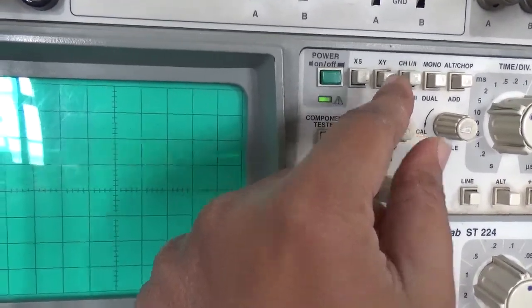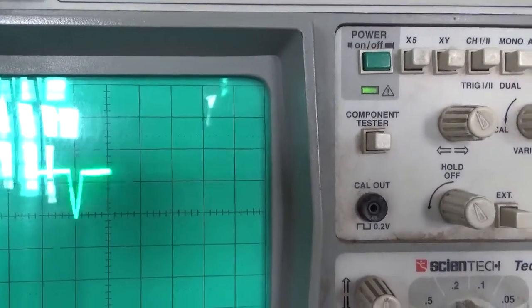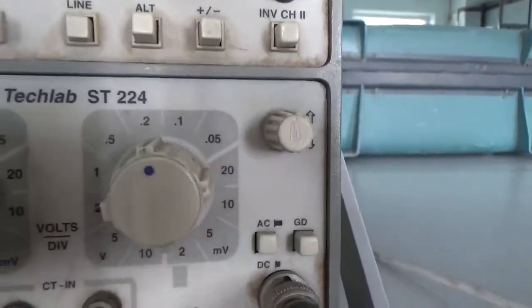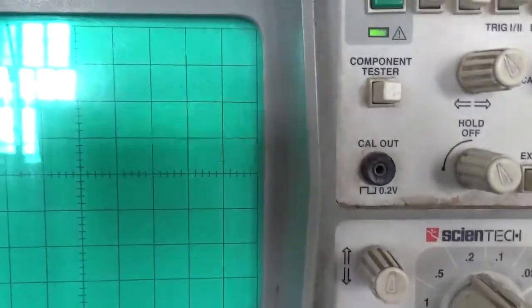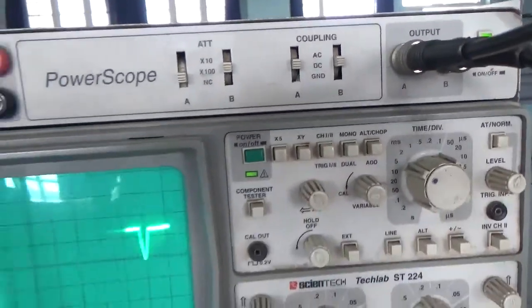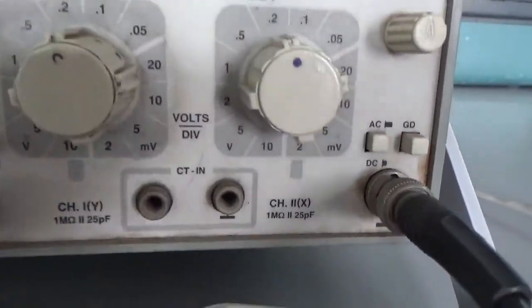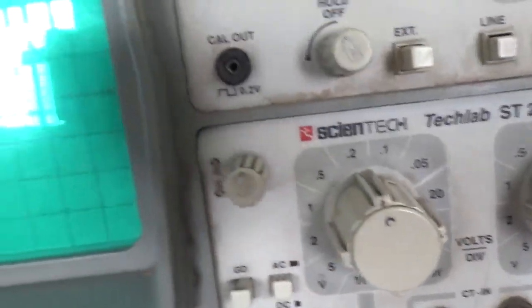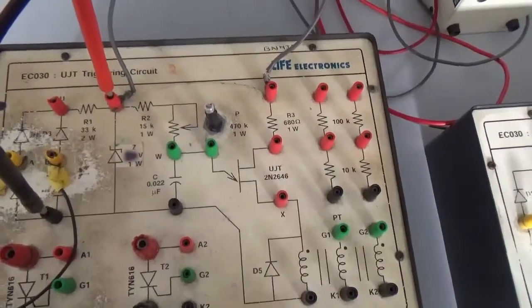The magnitude is going to be 1.4. If you check, it's 1.4 into the scale I have taken, which is 0.2, into 100. Whatever value you get, 1.4 into 0.2 is 0.28, so around 28. That magnitude you have to take for the voltage across the Zener diode.